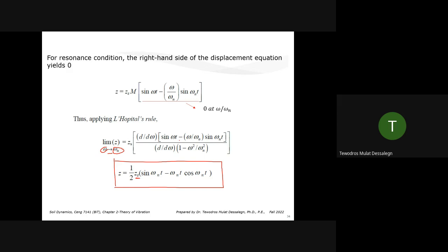When we discussed the first chapter, Introduction to Earthquake, we specifically mentioned an example on resonance. And that was the Mexico City earthquake. In the Mexico City earthquake, there was excessively large amplification of the bedrock motion through the soil, and the fundamental frequency was around 2 hertz, I think.